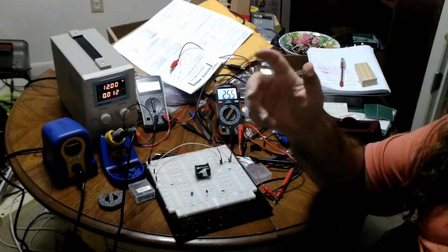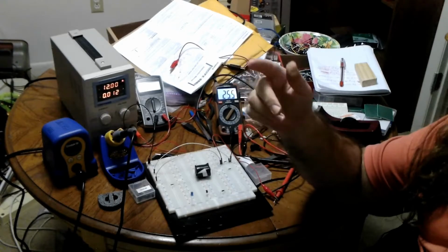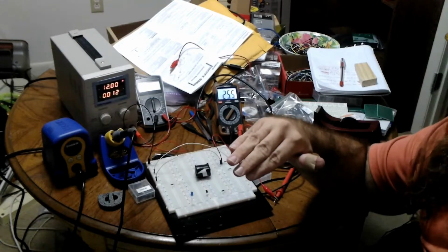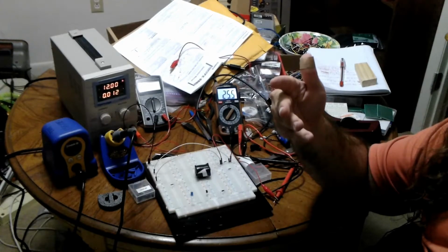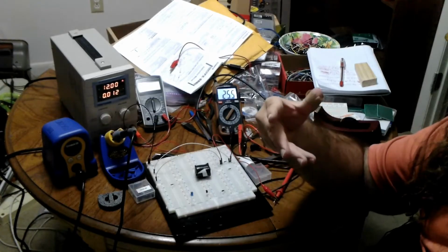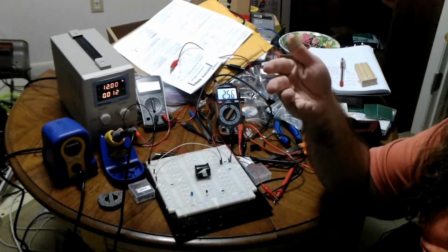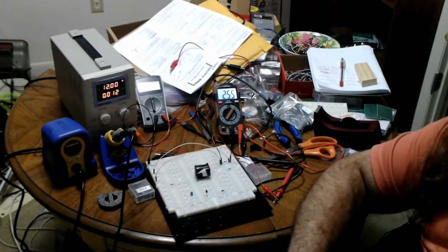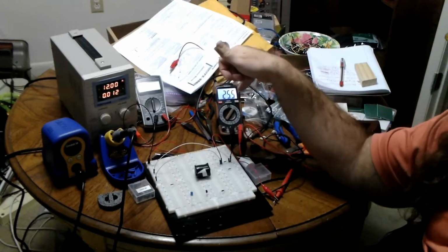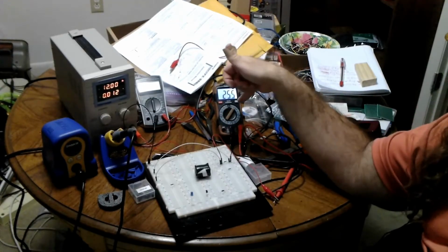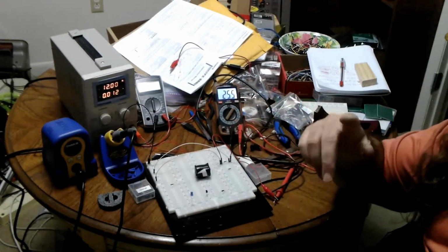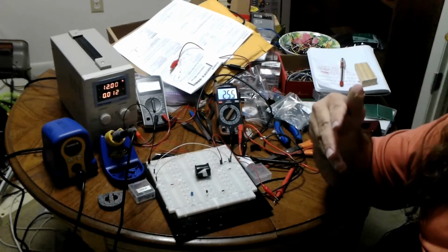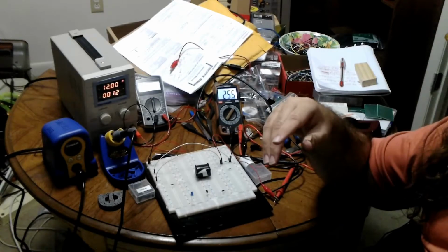Do you remember how we turn AC into DC? Step one is you take a diode and you block the negative parts. It wastes half your power, but it's all positive and zero, isn't it? Well, then, of course, you use a full bridge rectifier to put the negatives on the positives and smooth it out and so forth, but wait, it's just measuring. An AC signal is regular. It's a sinusoidal. And recall how these numbers are set just so it's clearly intended for wall power, which is going to be a nice sinusoidal. So if you block half of that sinusoidal, well, you know what you blocked. As long as you measure half, you know what the other half was.